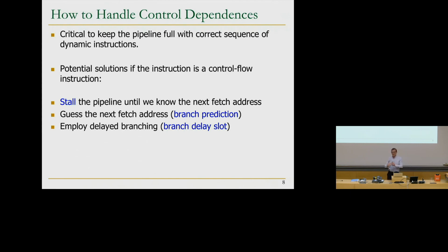So basically, this is called a delay slot. The branch doesn't immediately jump to the target if it needs to jump to the target, but always the next n instructions are executed. Let's say the next 3 instructions, which means that if your pipeline is 4 stages, you can put independent instructions in that delay slot, and they're going to be always executed.